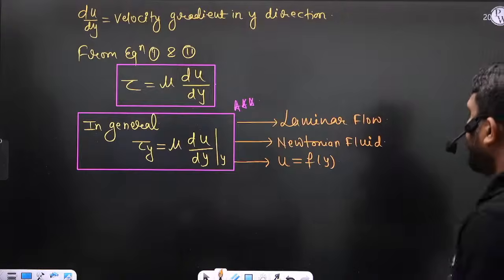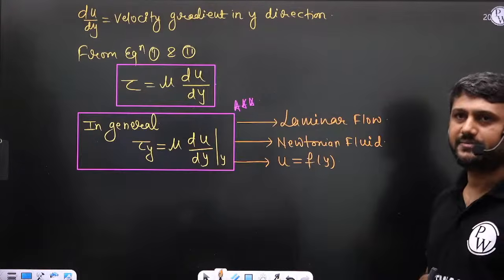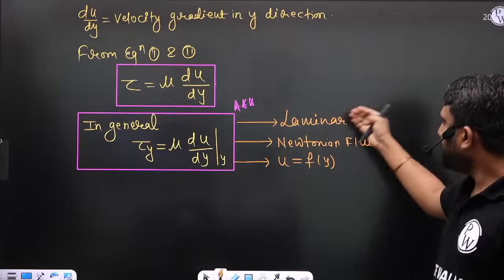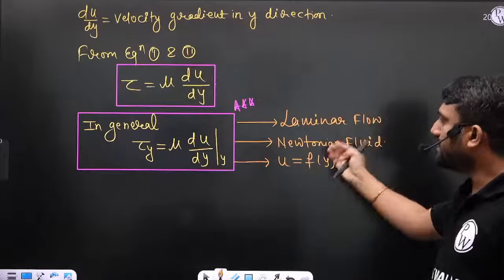Then you can use this Newton's law of viscosity mathematical expression. Flow must be laminar flow, fluid must be Newtonian fluid, and u must be a function of y.